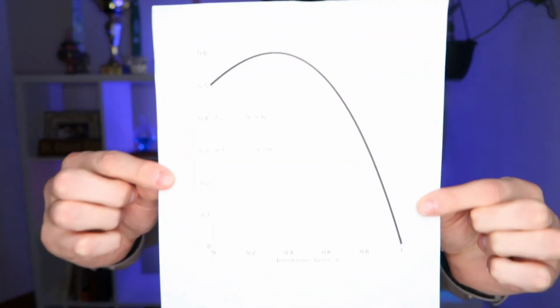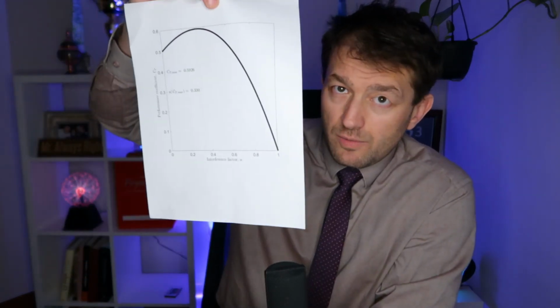Another thing that is maybe worth mentioning is if we go back to this graph, then we can also give an answer to a question: what would happen if a wind turbine is indeed a solid wall that I talked about at the beginning of this video, and it completely blocks the air? In other words, downstream velocity is 0. And that means interference factor is 0.